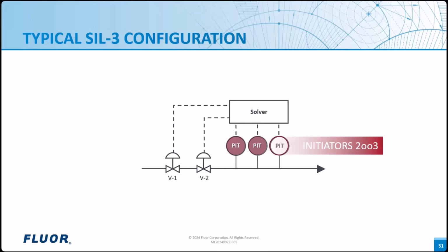The final elements, 2 emergency shutdown valves in this case, are used in a 1 out of 2 configuration, which means that one of the 2 valves must close to prevent the overpressure, i.e. closure of one valve is sufficient to be successful. In this case, it is cleared by cutting off the source of overpressure, i.e. the upstream flow, before the overpressure occurs. The HIPPS avoids having to relieve material to the flare, which avoids emissions during an upset and avoids modifications to the flare effluent handling systems.